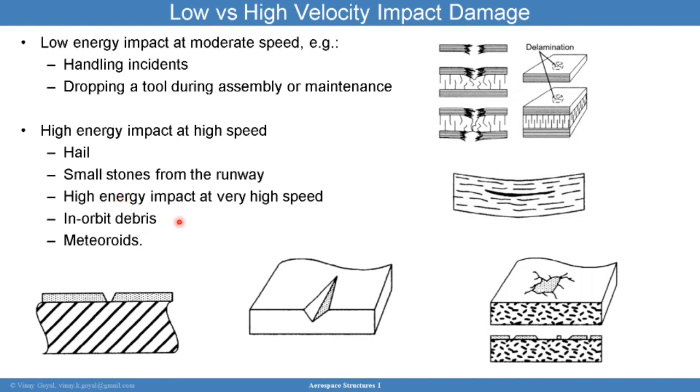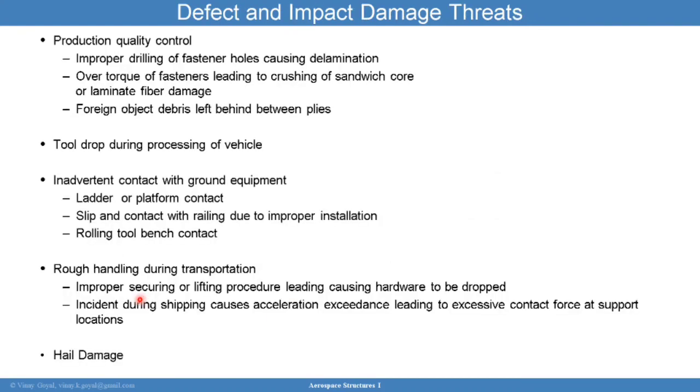Hail damage and lightning damage can actually puncture the composite, as you can see here, or chip away at the composite. It can cause a cleavage failure mode. It will just look like this, for example, so the fish is basically lifted out completely. And you could also have other types of damage. Drilling the fasteners can cause delamination.